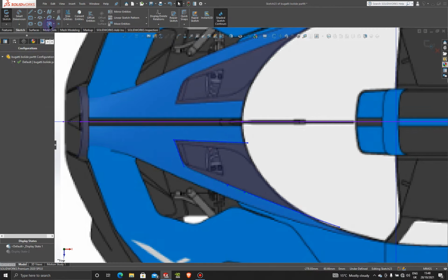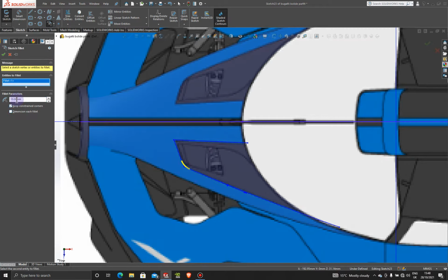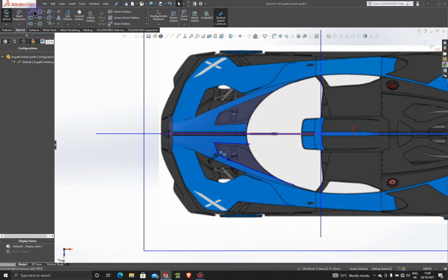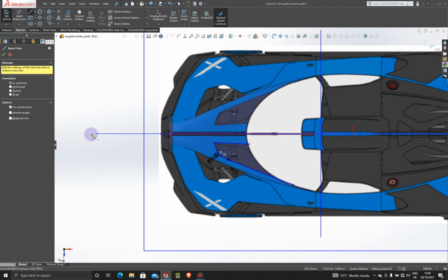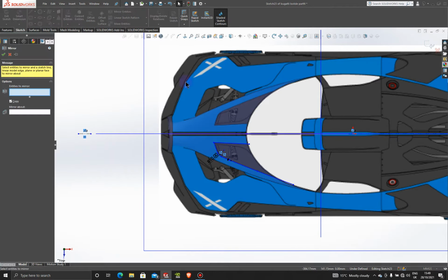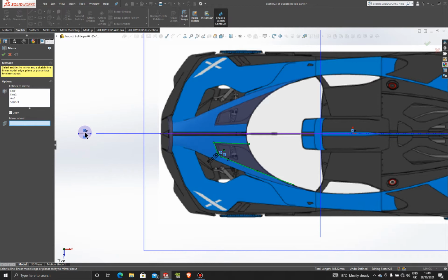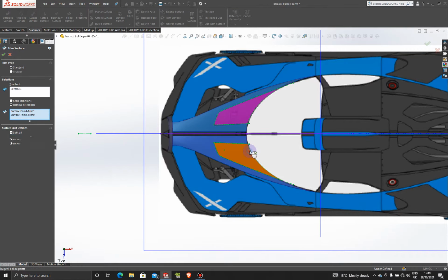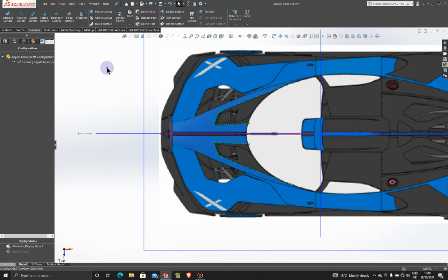And we're going to add our fillet on this corner. And a 10.00 millimeter fillet will be good for us. So we leave that. And of course, we want to mirror the sketch over these entities. So make sure you put that on that side, and let's mirror these entities over the other side. And we're going to mirror it over here. Okay, and then we just jump to surfaces, trim surface, and we get rid of these two here. All right, that looks good.